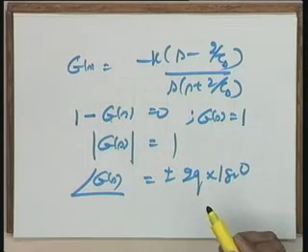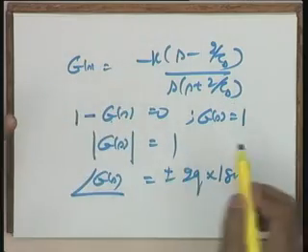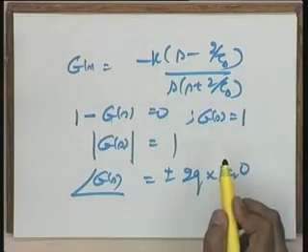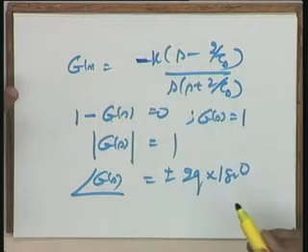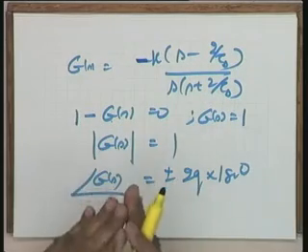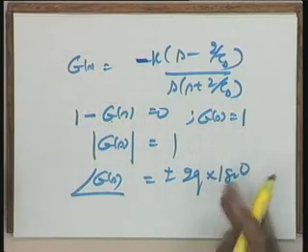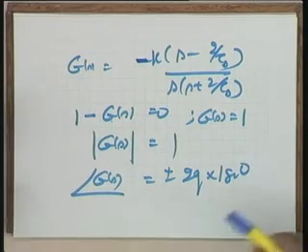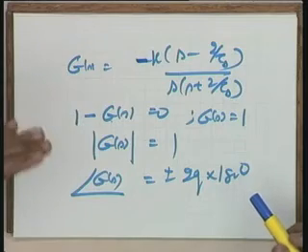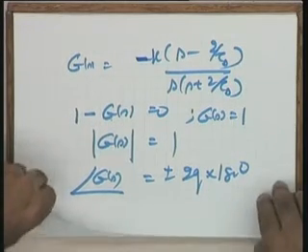Earlier it was G(s) equal to minus 1. Because it was minus 1, the requirement was odd multiple of 180 degrees. With this minus sign coming outside, it is an even multiple of 180 degrees. And if you take even multiple of 180 degrees, the rules will change now. Wherever 2q plus 1 appears in the rules, it will become 2q because now it is an even multiple of 180 degrees. So, give me the root locus sketch for this example, please.